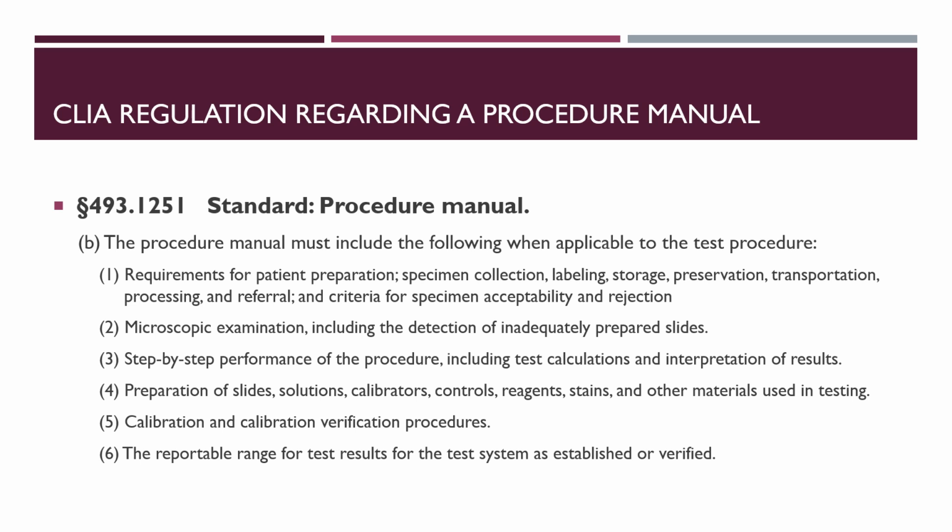It should also include any sort of calibration or calibration verification procedures that may be for that particular instrument, if there are any. It should include the reportable ranges. So is this test only valid if the result is between 10 and 20? If it's beyond 20, what do you need to do? Do you have an additional test that has to be performed, or is it verified by a certain way? So these are all things that have to be included in that procedure.